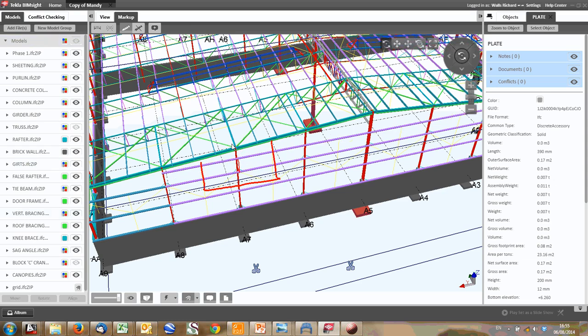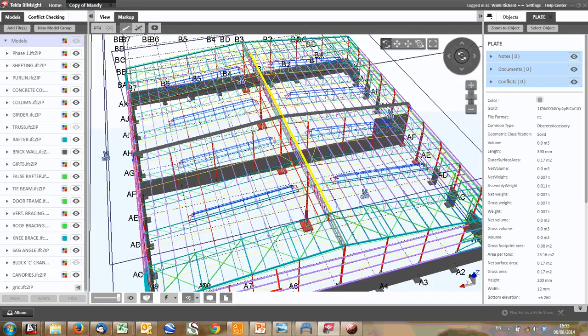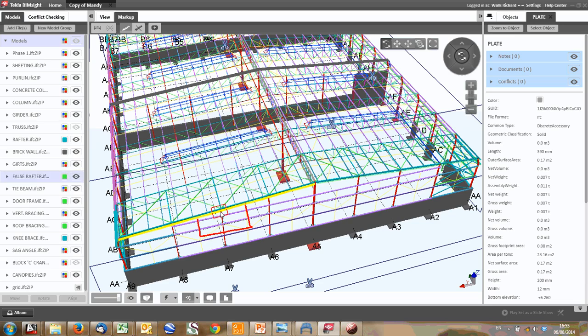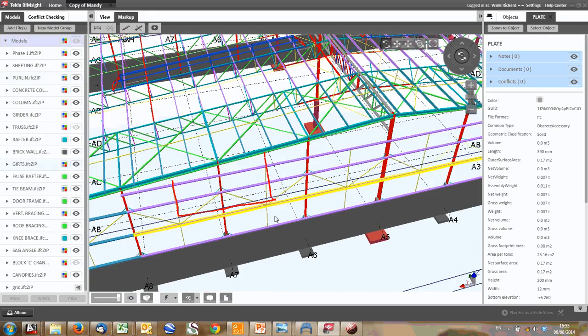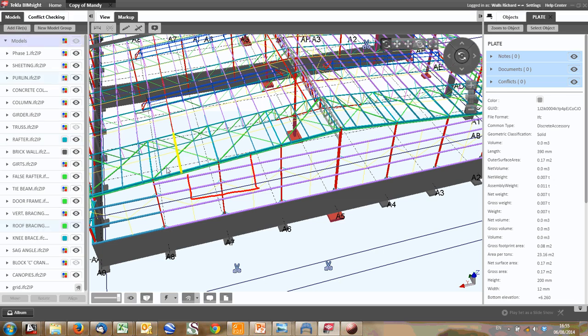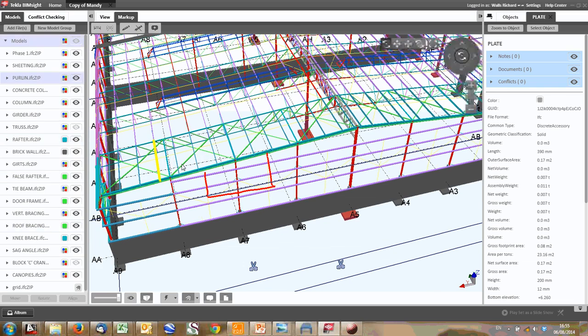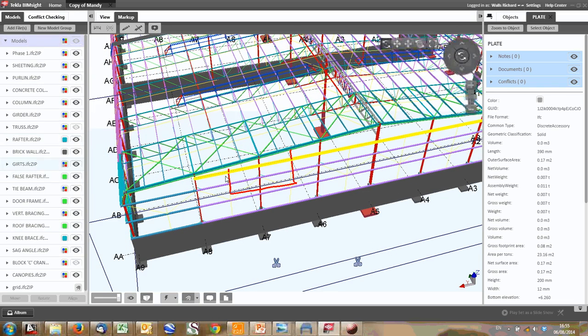It's just pressure of the wind times area. But remember, this is for pressure only on this face. If this brace bay is carrying the other face as well, you need to add in that face to this load. But you'll see why just now we actually have two braced bays for the gable, but only one for the trusses, right? So this load now will come into this brace, vertical, this horizontal brace all the way along the top. And there we are.